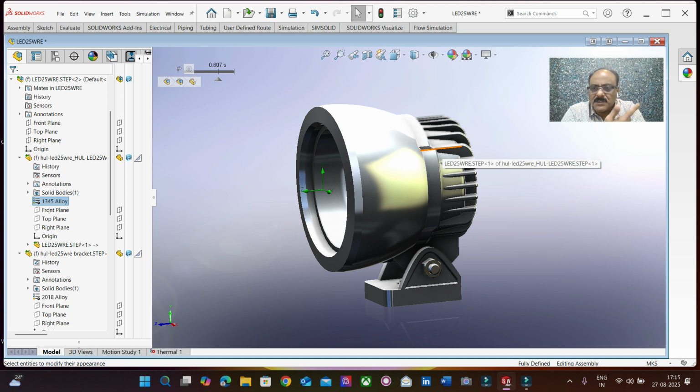We can also key in the shear, triaxial shear stress parameters, and we can also define the bulk modulus. We can also define the strain portions. So when we perform a nonlinear simulation, the material data that we give should also be accordingly.